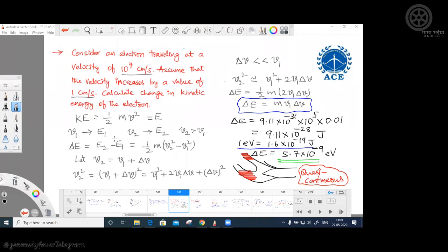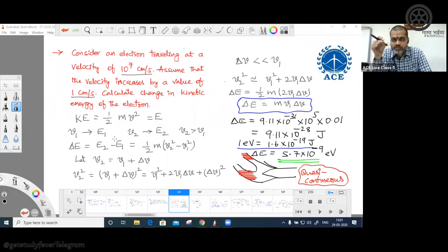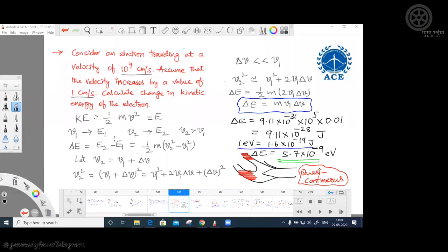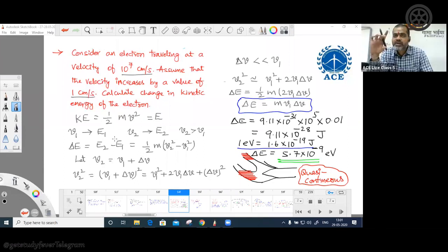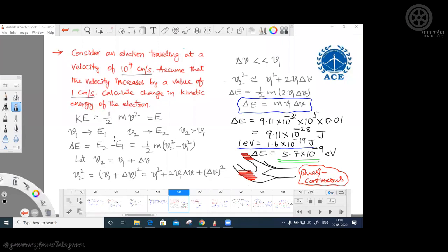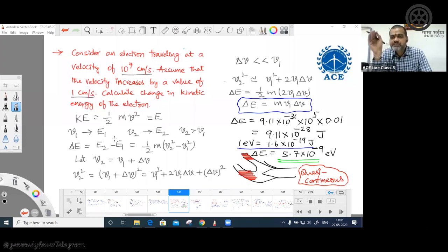Try to understand. Physically, it represents, I'm repeating the statement that I've given, please listen carefully: it is the energy level where exactly half of the available energy levels are occupied once T is greater than 0 Kelvin. Okay, sir. I am not saying that wherever the forbidden band is there are no energy levels, but you have the energy levels in the valence band and conduction band, separated by that gap. So available states will be in the valence band and conduction band only.